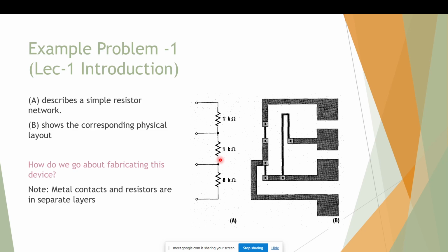Say I want to fabricate this circuit in the nanofabrication facility that we have here at Sense. What I will do first is make a layout of it. I'll open some software like KLayout and make a GDS file of it. This is just a circuit with circuit symbols, so we need to have a physical layout in mind when we want to make a device.